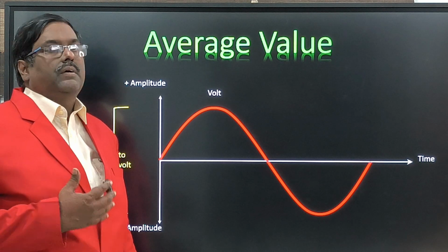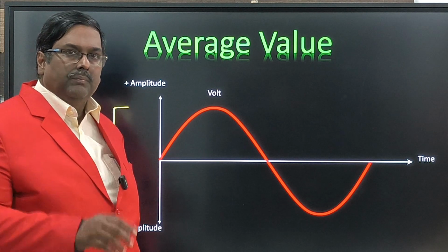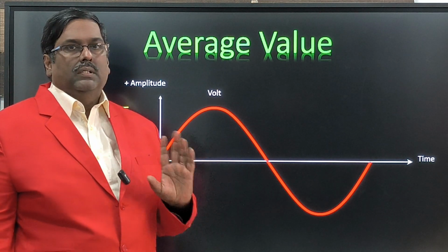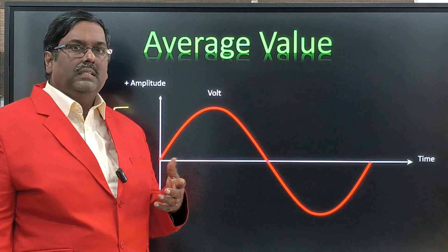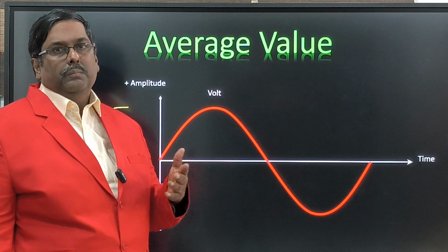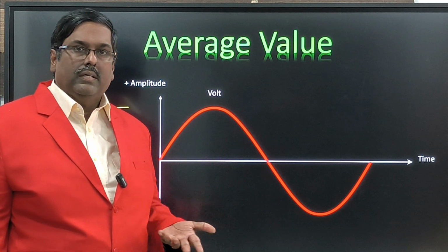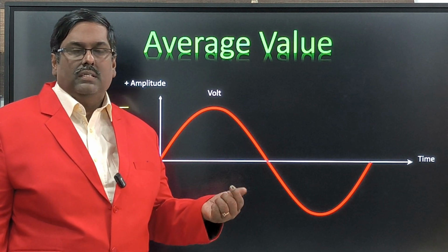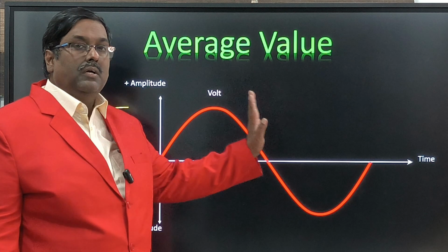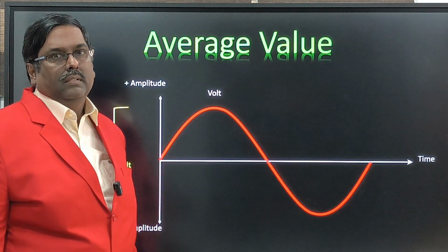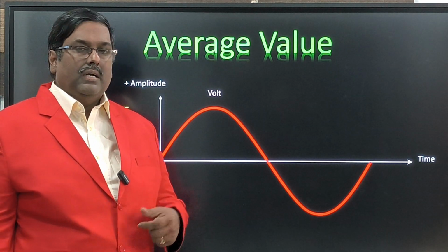DC power wattage, everybody knows. If suppose one company sold you a motor, with this much horsepower or this much wattage, this power is in DC. But the same wattage unit, you cannot mention as AC wattage and DC wattage. Power should be power, right? Whether it is DC or AC, the power should be wattage. We cannot say DC wattage is different and AC wattage is different. So we convert this AC cycle to its equivalent DC, and then calculate the power. For that reason only this RMS has come. We will see how the RMS is developed and what its significance is.